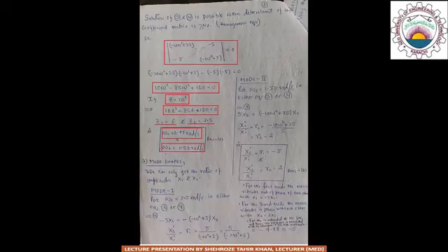Next, we will find out the mode shapes, which are basically the displacement or deformation patterns which a vibrating body or structure will acquire when it is made to vibrate at a given frequency. The mode shapes of the system are found by simply substituting the values of omega 1 and omega 2 in equations 3 or 4.